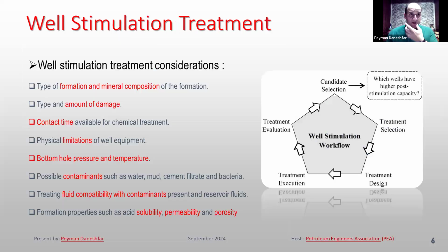So in a well stimulation treatment, some parameters are important for us. We should consider all of them: the formation and mineral composition, what type of damage and the amount of damage, the contact time of the chemical that we want to use to cure the well, and also limitations of the well equipment.